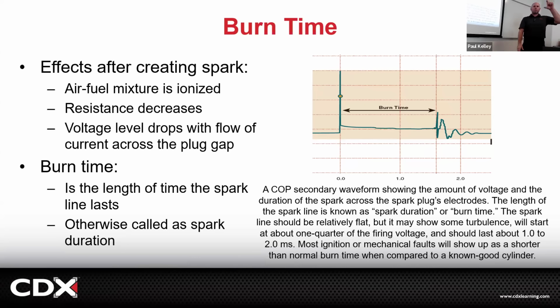And it all might just be because your spark plug gap is too wide and you're like, what? That was it? I just needed spark plugs? Yeah, that happens. That will change your emissions levels on your tailpipe test for your smog. Absolutely.